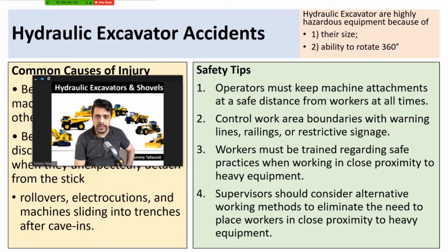Supervisors should consider alternative working methods to eliminate the need to place workers in close proximity, right? So that's what I was talking about. Try to shift your workers, ask them to do something else which is far enough from the excavator's maneuver area, because you never know. Most of the accidents, when you ask people, they initially thought it was totally safe for them because they were watching, the operator is skillful, and so on.